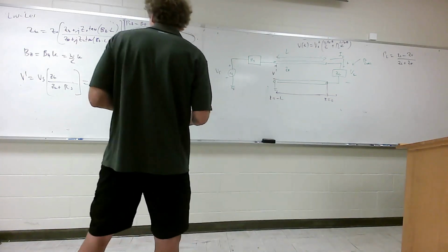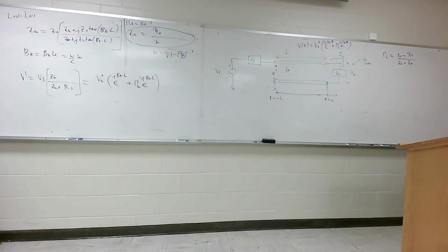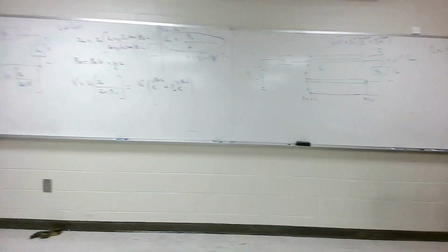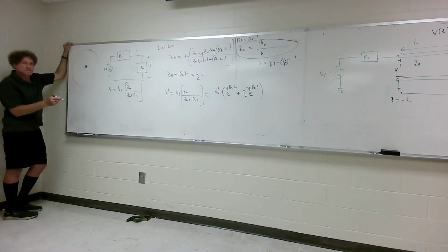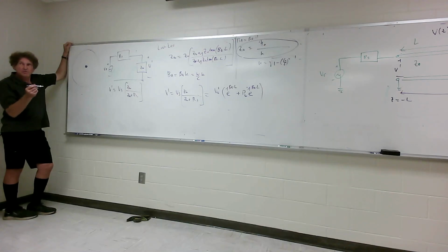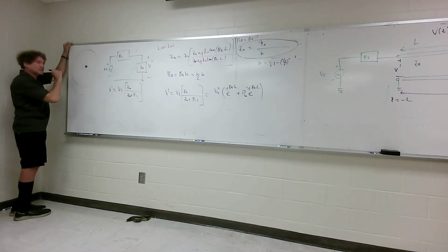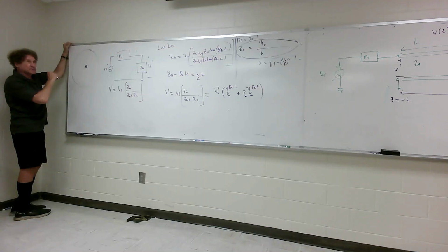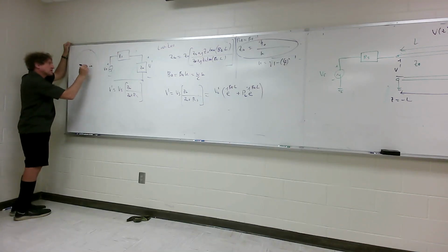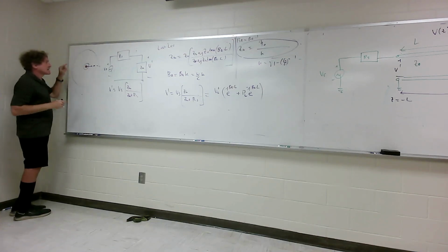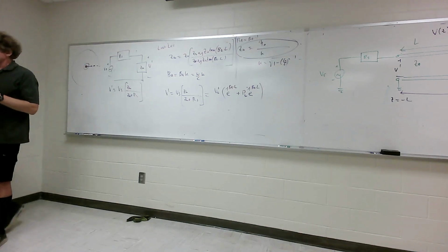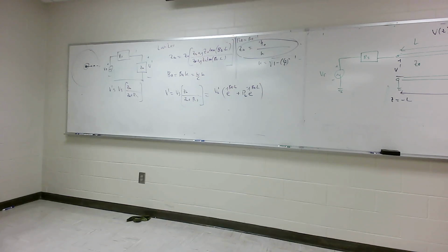I'm just going to try to make sure you see this. If we take a look at a standard transmission line, we've got a little core here, and then you have an outer diameter. If you looked at the field values, just plotted the electric field, a vector field plot, you would see a very large field here, and as you get further away it's smaller, almost nothing in relative scale at the outer point. Y'all with me? Very high in the center. Well, the dielectric breakdown in a region is the thing you worry about exceeding.